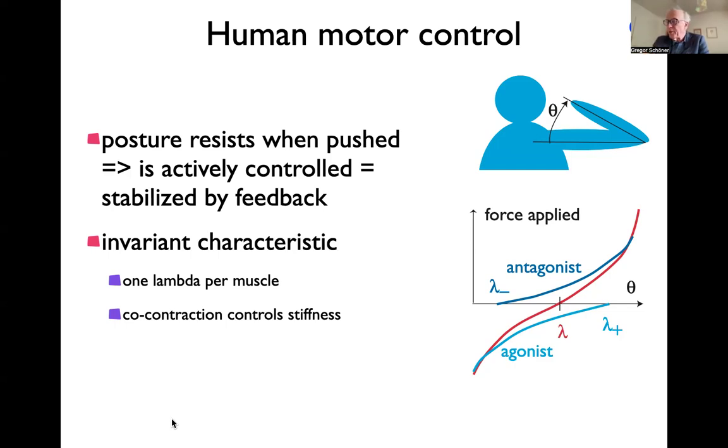It's so difficult because when you do that, the normal control doesn't work so well, right? The normal control would be moving your arm around, and now you have these springs that are really sluggish, and as you're trying to move the arm to a location, you have to ask, does it overshoot? Does it oscillate? Does it actually even get there? It will get there with delay and all kinds of problems. So to reconcile targeted movement with this property of being compliant, that's the challenge here.